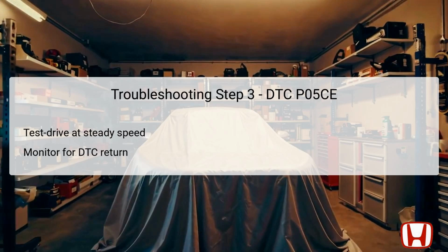The next step in troubleshooting DTC P05CE involves test driving the vehicle at a steady speed between 25 to 75 miles per hour, 40 to 120 kilometers per hour. This steady speed test is crucial. It allows for monitoring how the vehicle behaves under normal driving conditions. The vehicle should be driven for a minimum of 10 seconds to ensure that consistent data can be captured. This driving procedure simulates conditions under which the engine's VTC system should ideally function.